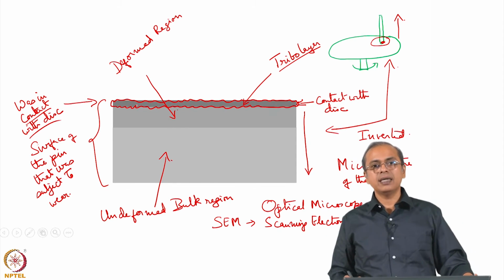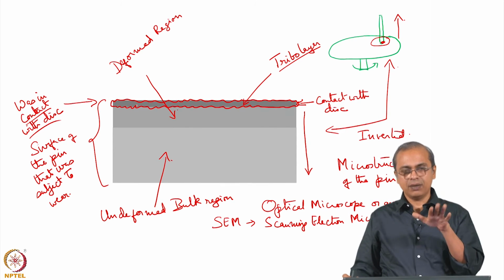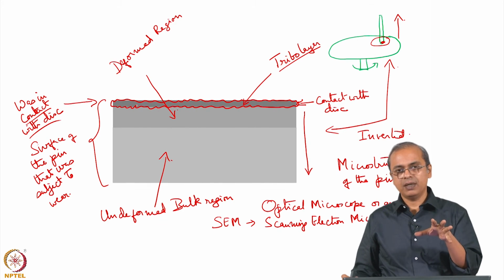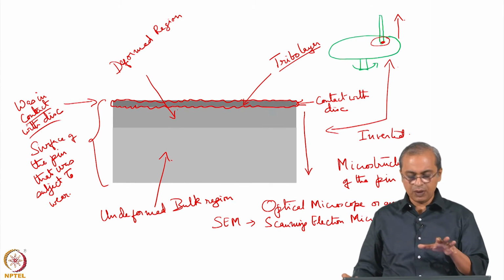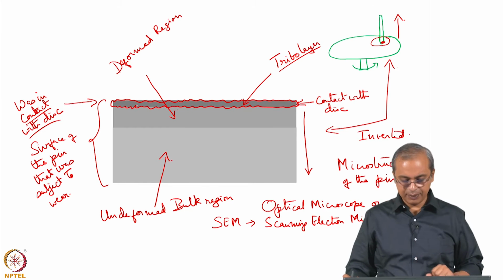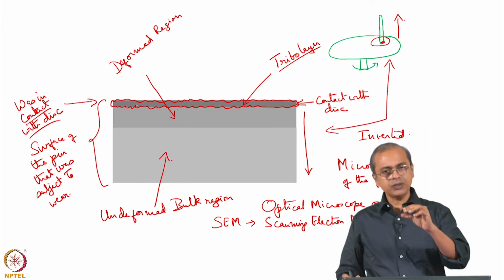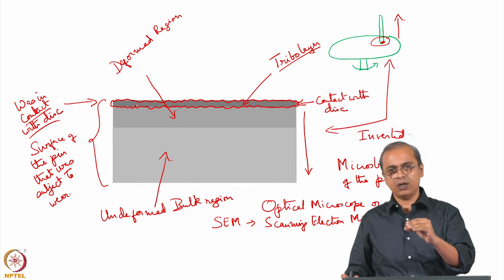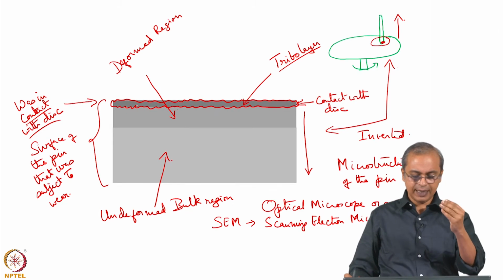This is called the tribo layer. It is the layer that is having some kind of broken down material of the parent material that you are testing, and a fair bit of it is going to be oxide because of its oxidation. You exposed it to conditions that are favorable to oxidation, so it is very likely that it will be in oxidized form. So that is the tribo layer, that is usually relatively thin, because that is how far the oxide penetration, oxygen penetration and so on, happens.